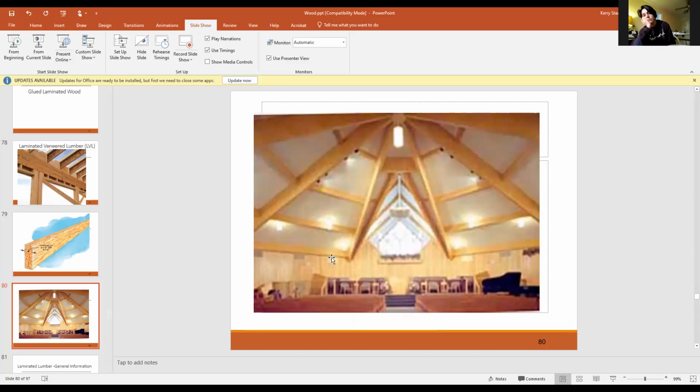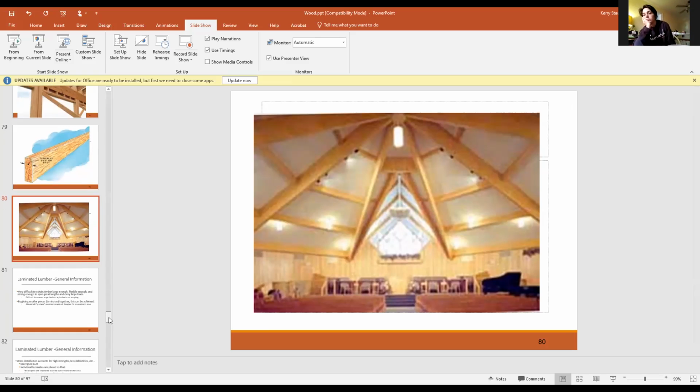So if you were to try to do a heavy timber frame type of construction with this type of spans and with these type of loads, can you imagine the difficulty that you would have finding logs that you could cut that would be long enough and straight enough and even strong enough? Because remember, logs naturally have knots and discontinuities, which are weaknesses. So it would be very difficult for us to do this. Now, I'm not saying that they don't, but it's much more difficult to find.